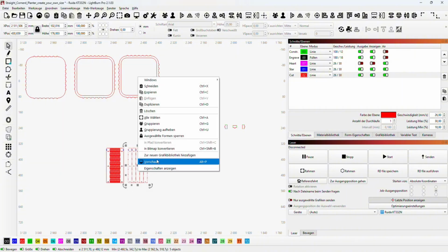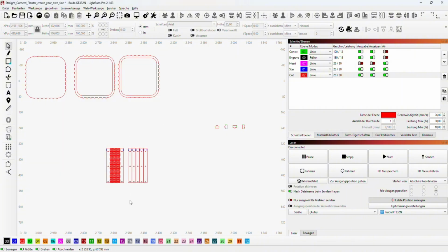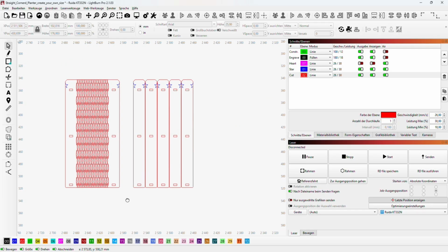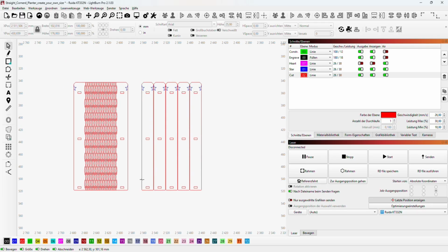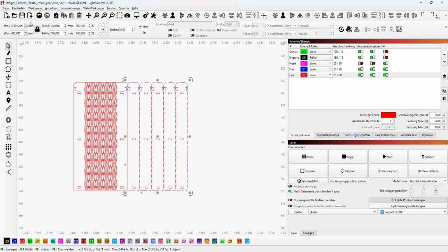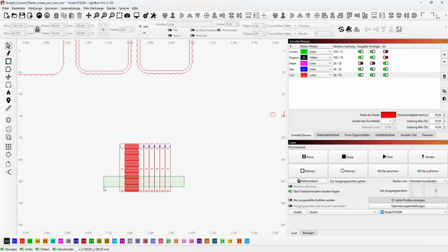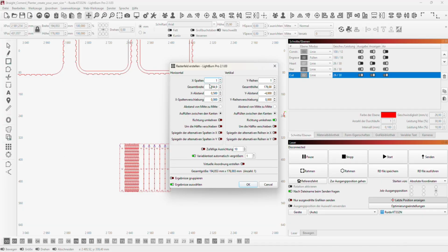Group the slats, then drag them next to the corner piece using click and snap. Finally, enter -0.5 millimeters in the x-coordinate to restore the correct spacing. Then align it to the same height as the bottom edge. Now use the linear array function to create 4 additional copies.